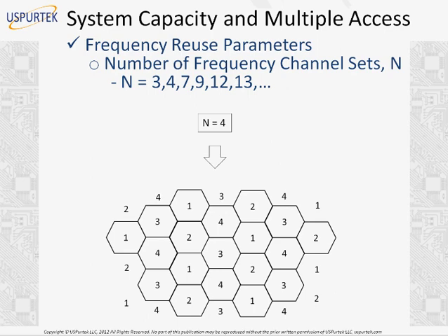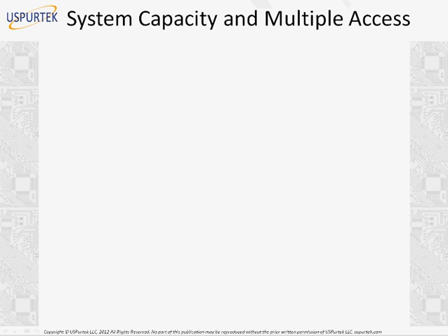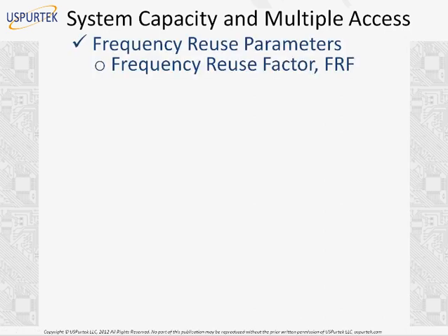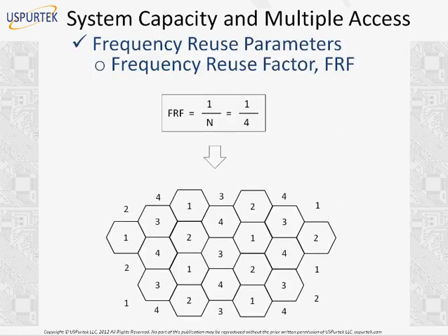Time slot allocation will depend on what standard you use, whether GSM, CDMA, or FDMA at all, because in CDMA you don't use FDMA. In GSM or LTE, it depends on what type of time slots you're using. Those will be covered in future webinars when we cover each protocol in more detail. But here our focus is how we reuse frequency spectrum in different cells to avoid co-channel interference.